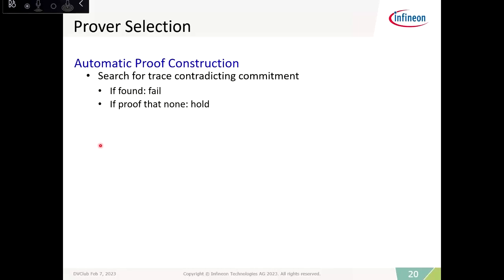Given that the examination window of a property handled by a bounded model checker typically just has at most a few hundred cycles, it is understood that the 32-bit counter cannot be shown to overflow within a witness trace from a reset. In contrast, with a set of 3 separate properties, one for initialization of the counter, one for incrementation, and one for the overflow case, the counter is exhaustively verified, where the second and the last property are only provable by the prover of group 1, not starting from a reset.